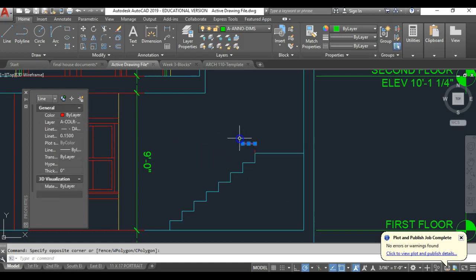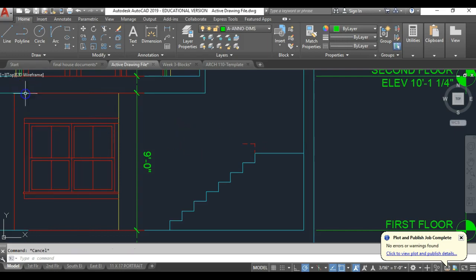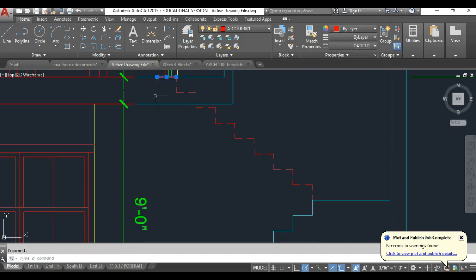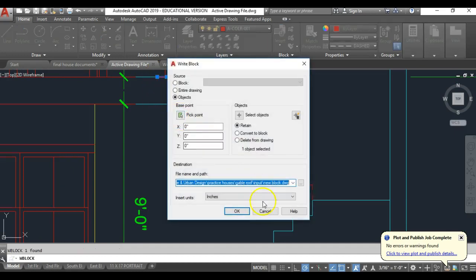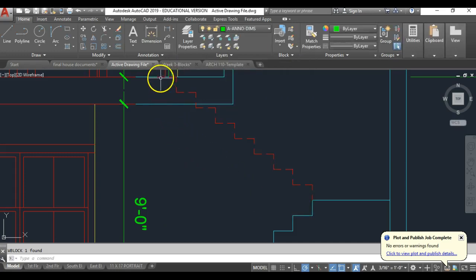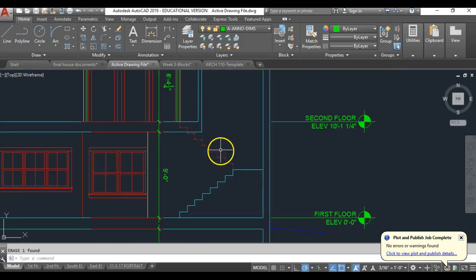So you notice I might have done that quickly, but we can see when I select it, this line type scale is 0.15 and it's a dotted line. I can close that. I don't need it anymore because I'll just copy this along. I'll go to copy or CO, enter, and copy this all the way up. Just right up to there, and we actually don't need that top bit of line. It's probably best just to select it and erase it. Oops, I wrote the wrong letter there, I think. And try again, erase it. There we go. And just get that dotted line going straight up through.